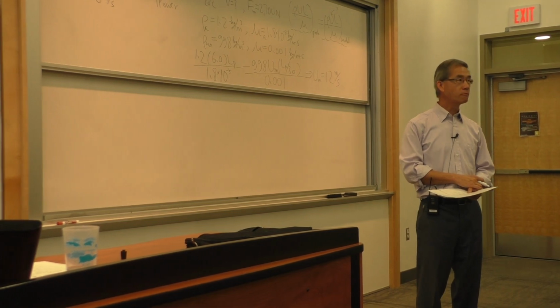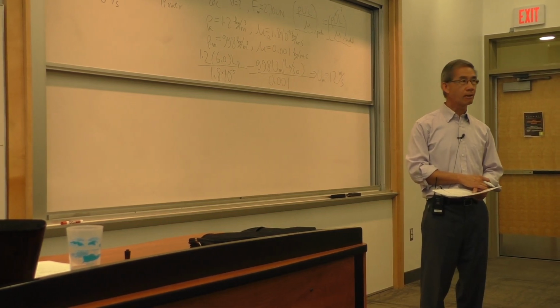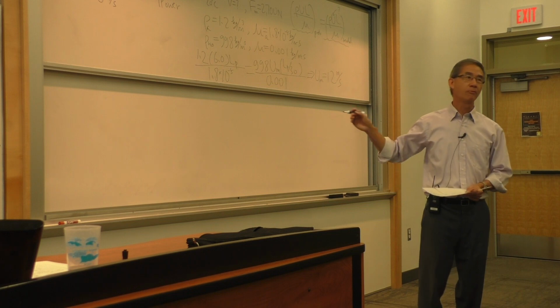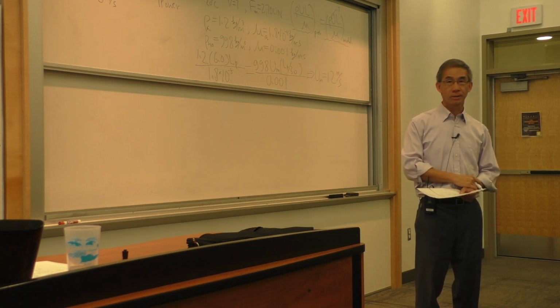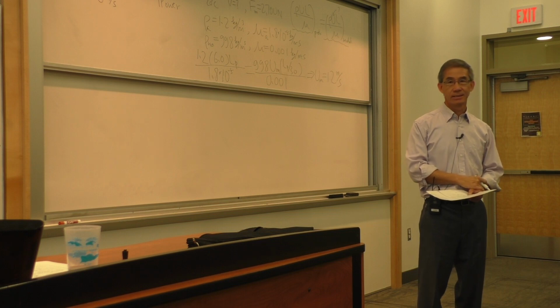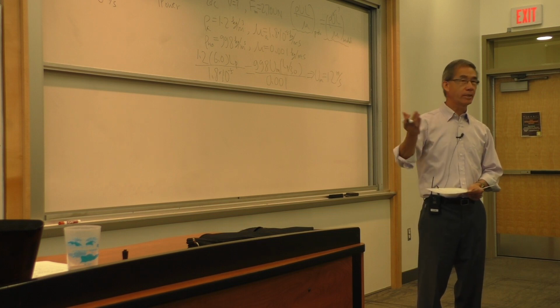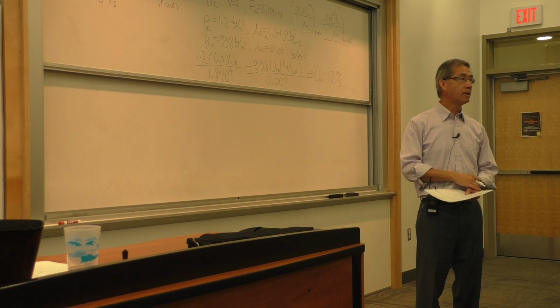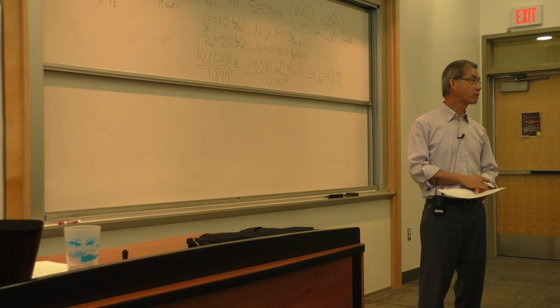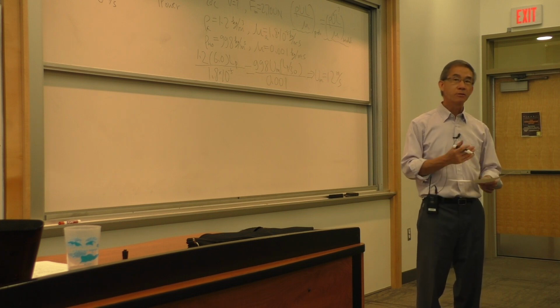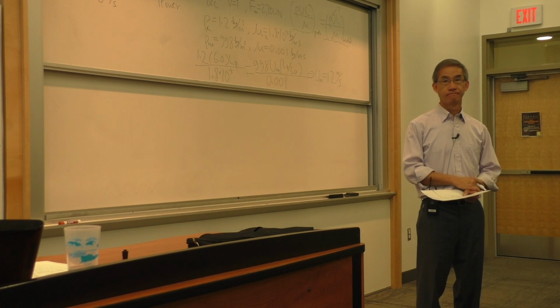You could. You will find very quickly that there are a lot of limitations. This is but one out of thousands of examples where you can match those parameters relatively easily. Your homework, which involves an airplane, which I have explained, and also involves testing an automobile at smaller scale in a wind tunnel, we will find it's very difficult to match those dimensionless parameters.